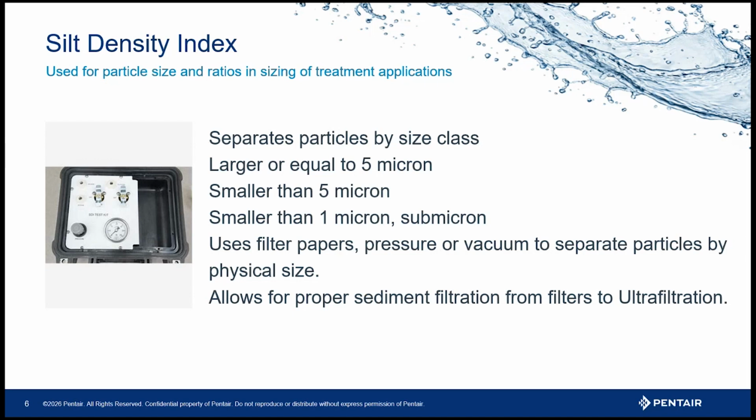Run the raw water through a 1 micron filter paper. You can buy those at science surplus stores and places like that. Collect the filtered sample, not the solid. Any color left means you have submicron particulate. This is something you can set up and let it filter down while you do other things and see what's there. So those are some field processes you can use to evaluate the waters you're on when you run into those tough colored water situations. So, solutions to colored water.